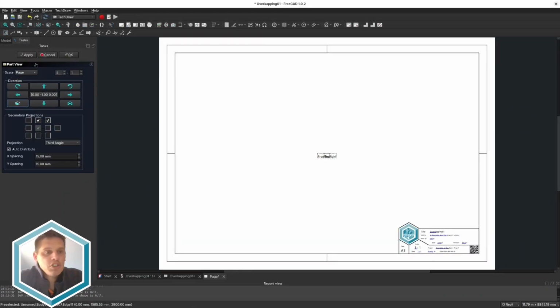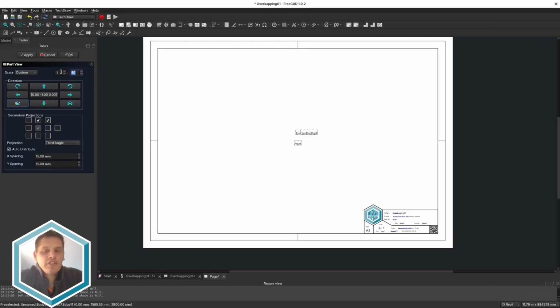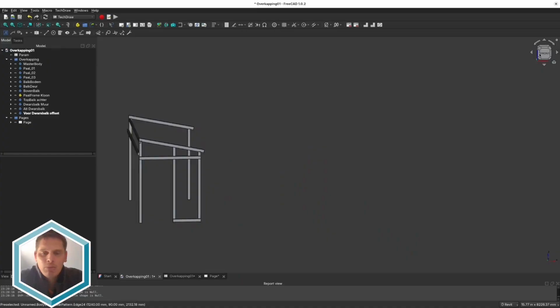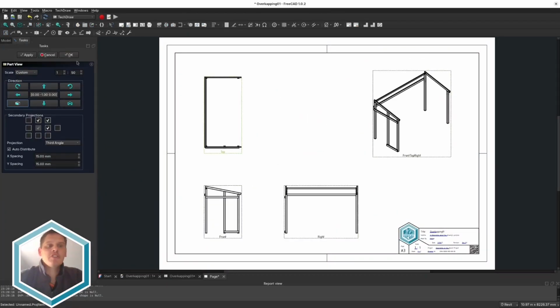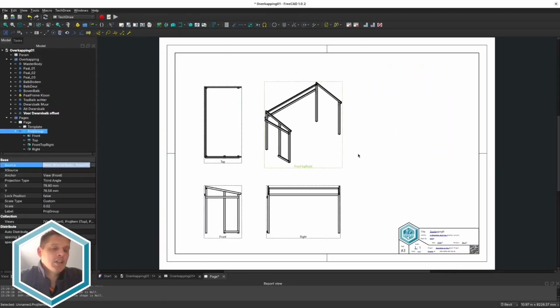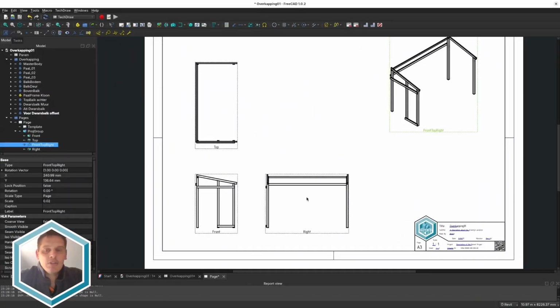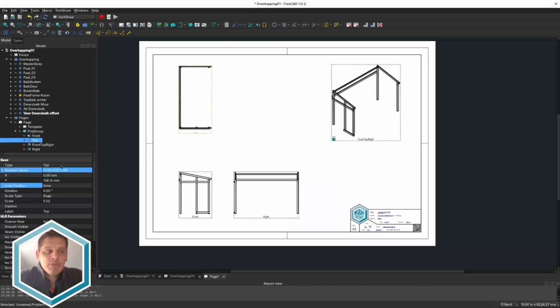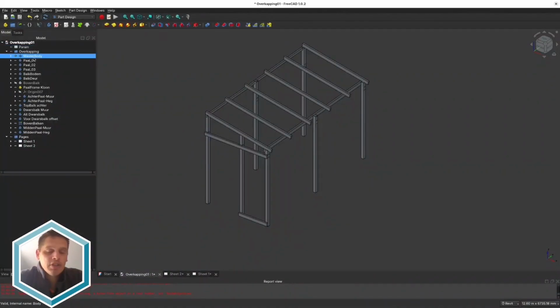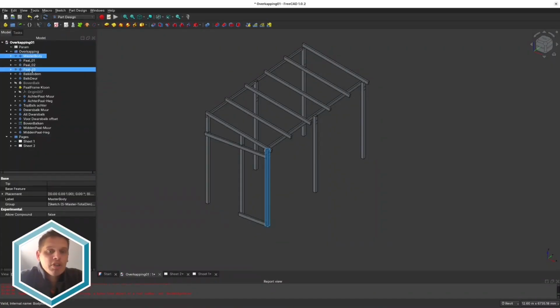Making my first sheet. I like to set the scale on the page level so that in my title box I have a few values, and the scale value is one that takes the scale of the page itself. And also it allows the views that I make. If I choose page and I set up the page scale correctly, basically it's hassle free. I set the scale once on the page, and all my other views, if I leave them at page, come out nicely. So that's what I do.